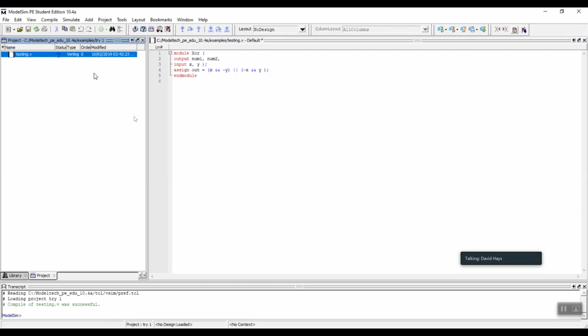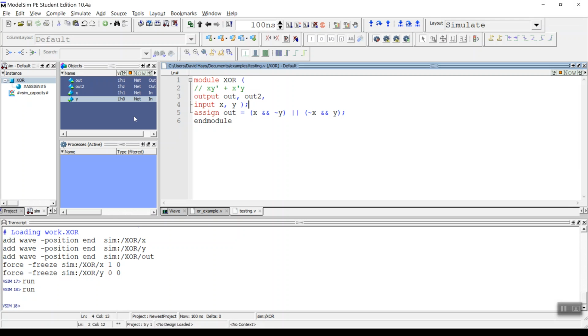I would click over in the code window on your right hand side, and then click the little diskette. I'm not even sure where the save is for the individual file. The floppy diskette in the upper left hand corner. Okay, now compile it. Then you can right click on that to simulate it.